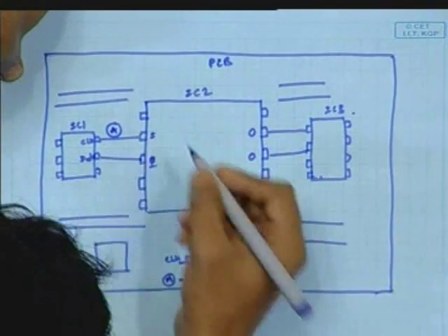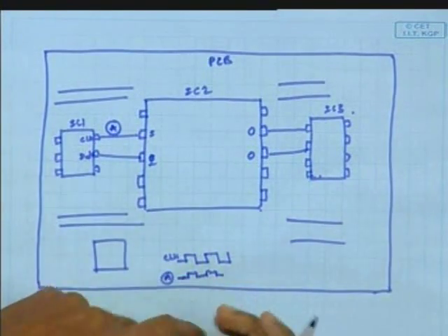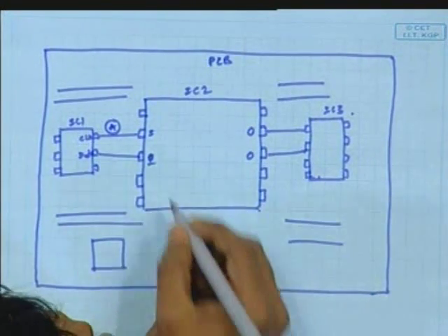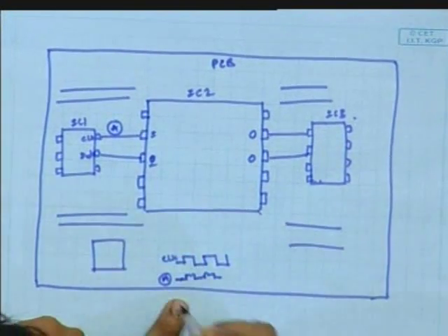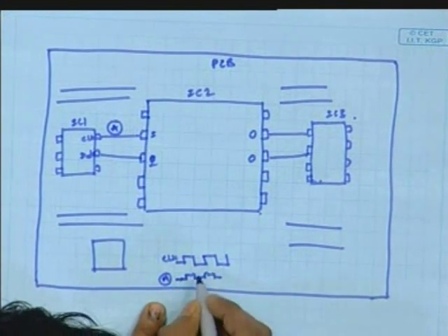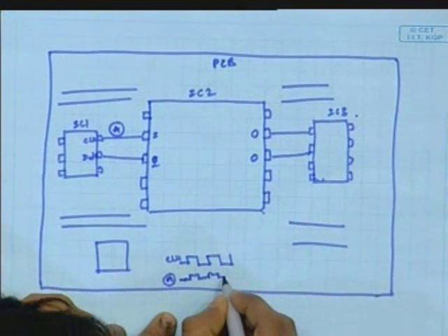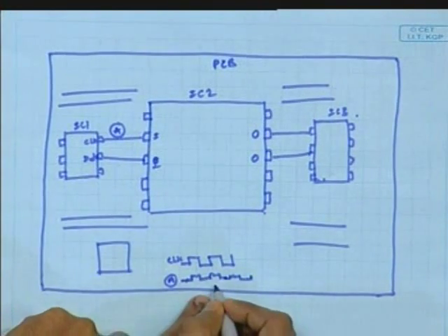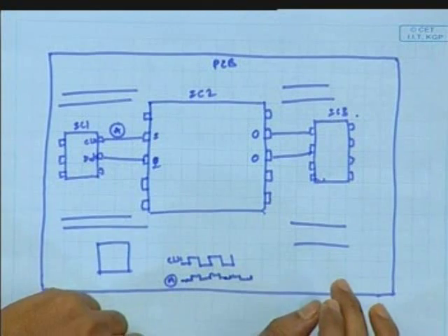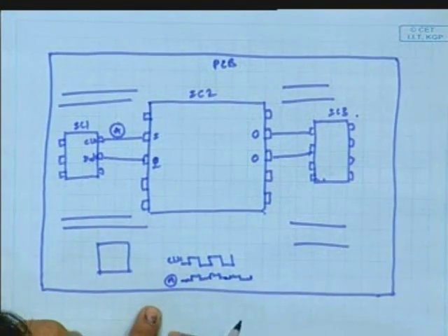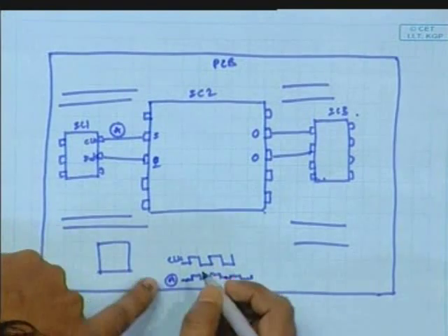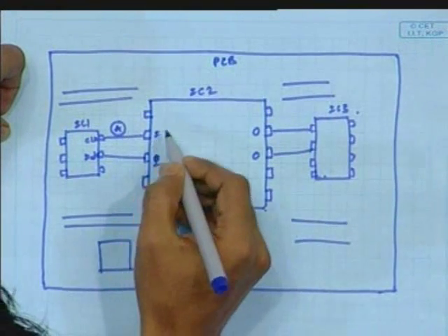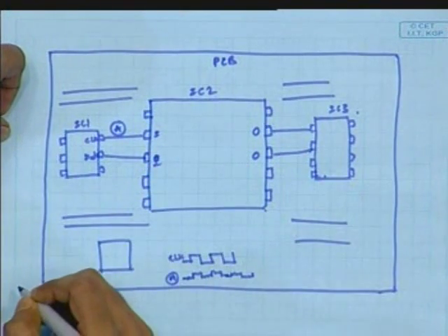We have to clean, we have to rectify, meaning we have to get a clean signal from this noisy signal, right? So we'll do that by using an IO buffer here. Because consider this signal: if the noise level is very high, at that time it will be something like this. So if we want to drive one flip flop using this clock, that flip flop will not be driven properly. So you have to get the clean signal from this signal. So how to get that? We'll get the clean signal using the input buffer, because this is the input of this IC. So we will call this buffer the input buffer, input type buffer.